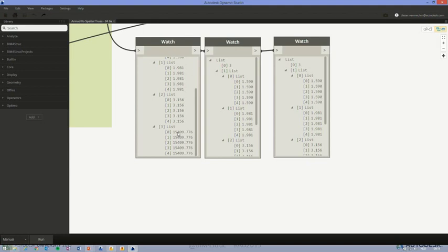So what it is doing at the moment is it's taking all these values. The results are returned, so that weight score. Then the genetic algorithm sees that the weight score is not optimal. It's not the lowest values. So it makes crossover and mutation between the initial values and generates a new truss height value, brings it back into that calculation, and by result it makes a new model.